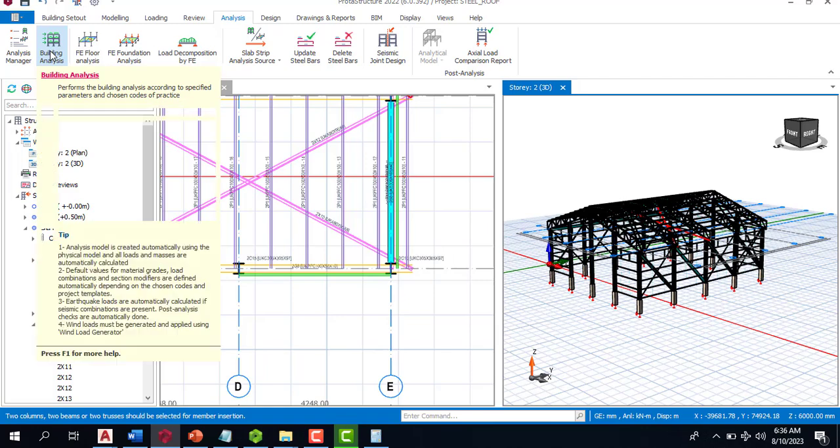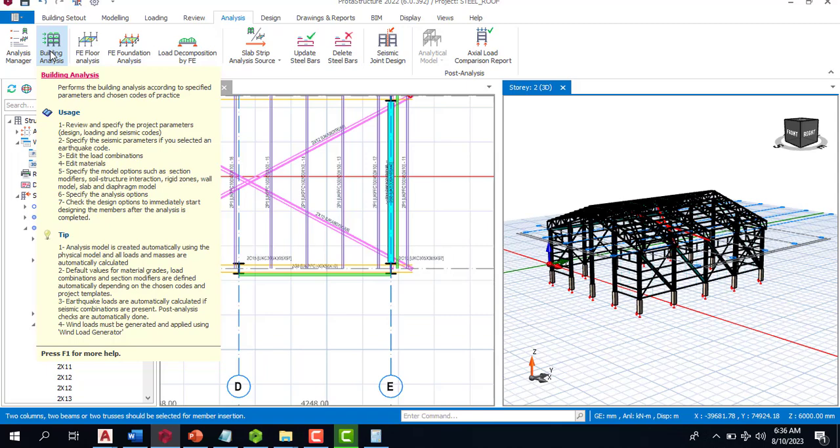So all you need to do is run the analysis and know the right steel cross sections, because by the time it analyzes it for you, you can play around with your utilization ratio and your slenderness ratio in order to strike a balance between them. Once you are able to strike a balance, that will definitely be the most economical and safe steel cross section.